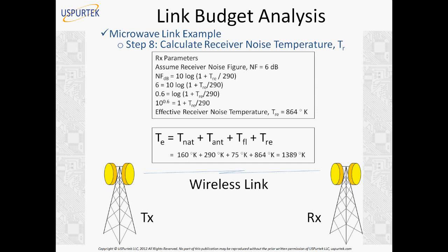So any organization, when it matures in the wireless communication industry, will have, over years of experience, some standard calculations already done. They know what type of signal level we need. But if you are coming into a new technology, like suppose LTE is being installed, 4G wireless broadband, this is entirely a new field, so somebody has to go through all these calculations again. LTE is not the same as GSM. It's a different frequency, different modulation techniques, and different application areas. Maybe you are putting more LTE towers in the downtown areas and fewer in the rural areas. So all these calculations do come into the picture.